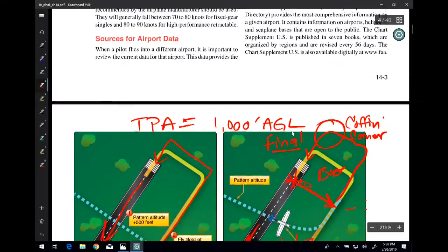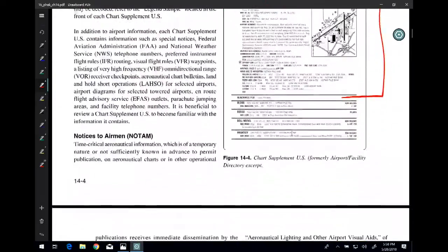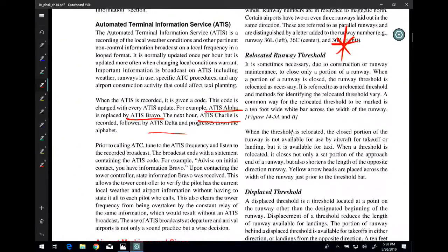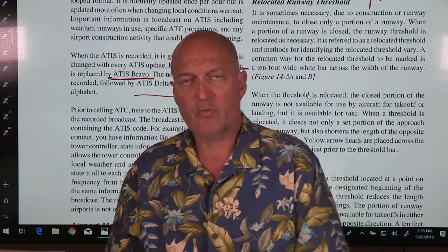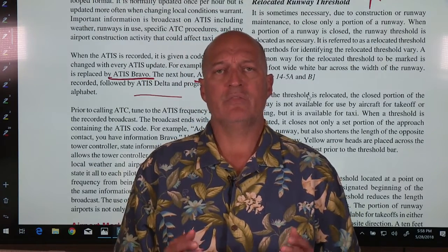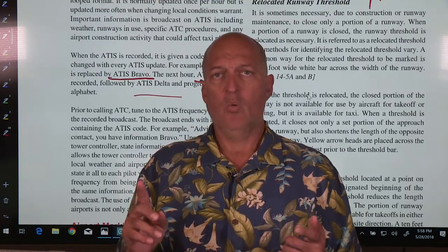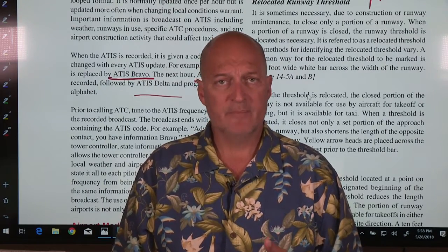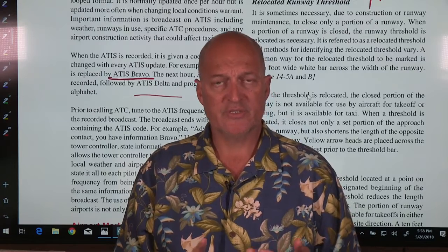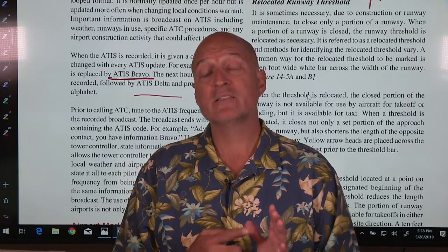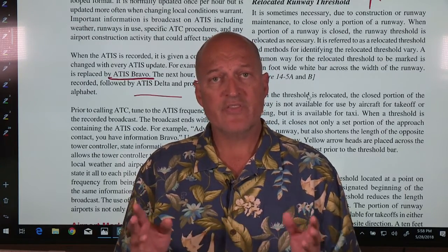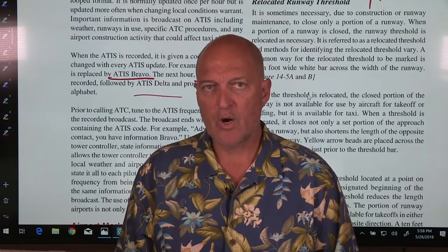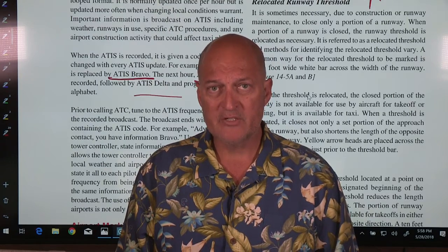we're going to come back to this airport piece, but I want to get over here to ATIS. One of the things we want when we're coming into an airport is the weather. We want to know what the winds are doing at that airport. What is our visibility? What are our sky conditions? What's the temperature? What is our altimeter setting? Those are the things that we normally get here. It's like a METAR. It's why we looked at those and why we memorized the format for METARs.